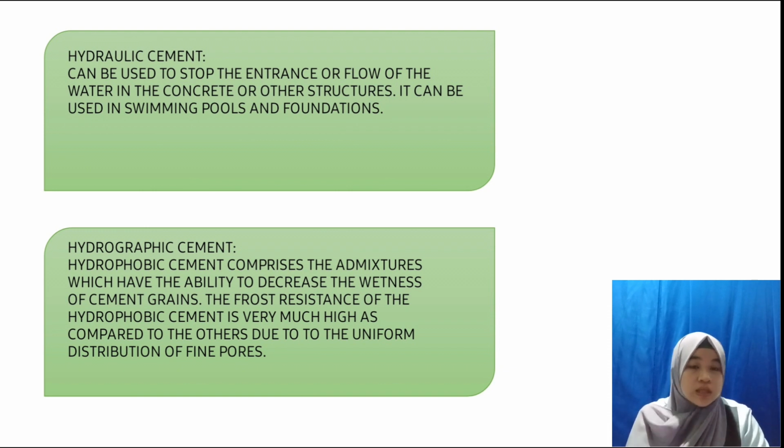It doesn't totally harden by then, but that is the minimum setting time of this cement. It is used widely in the construction industry, sealing structures below grade, and in situations where a structure can be affected by or submerged in water.